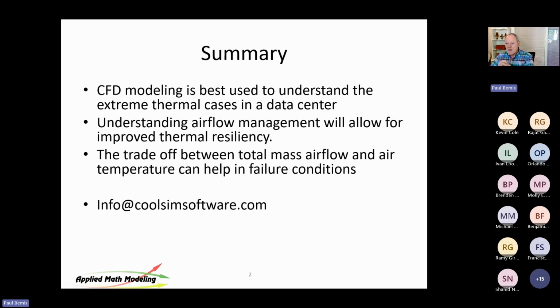So the cooling capacity of those units, a chiller, heat exchanger, whatever you want, will decline as the inlet temperature rises. And it declines non-linearly, but it at least declines a percent per degree F. So your cooling capacity will decline proportionate to the ambient outdoor air temp. And that's true of dry coolers.